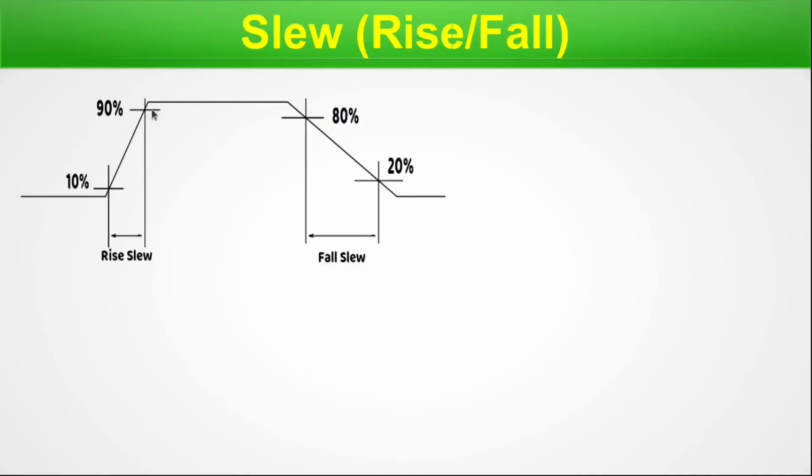Here 10%, here 90%, here 20%, and 80%. So these kinds of thresholds, that is lower threshold, upper threshold. Again here it is upper threshold and lower threshold. So these types of various threshold values are kept in the industry and in different files as per the design, and many other factors are there controlling them. Now if we cut a waveform here at 10% and here at 90%, why are we cutting? The reason is that this is not straight and then bends directly, because it is a capacitive action, so there will be a continuous bend, so we have to cut it somewhere, just to get a flat inclination.